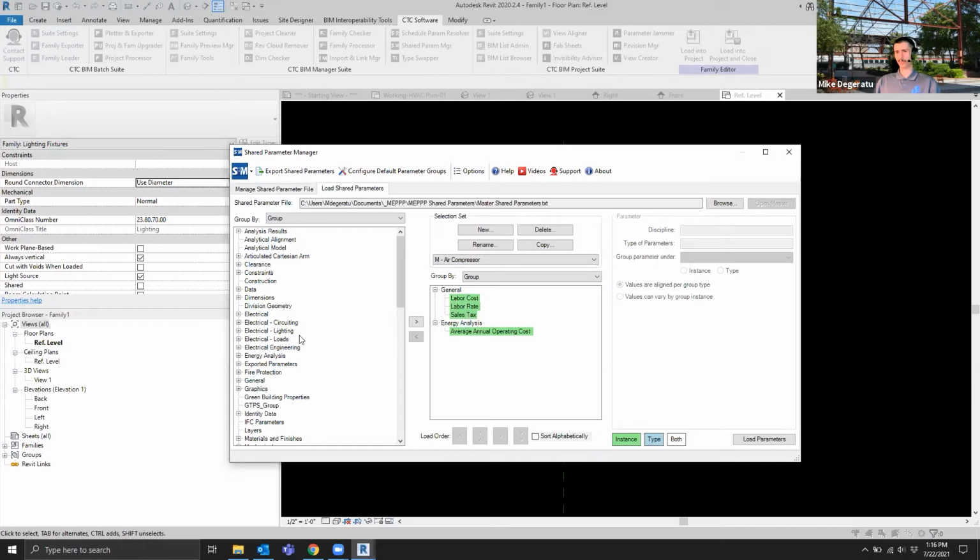And if you wanted to add more, let's say this is going to be air compressor. So I'm going to go to my mechanical parameters, and I'm just going to go straight mechanical. Now, once I open that up, we have a much more extensive list of share parameters than probably most companies. Some actually have it greater than this, but as I go through, as we see, there's a bunch of parameters, and I could probably scroll through exactly what I need, but I'm just going to add one for the duct connection. This is like, for example, like in a, actually no, it's air compressor. I'm sorry.